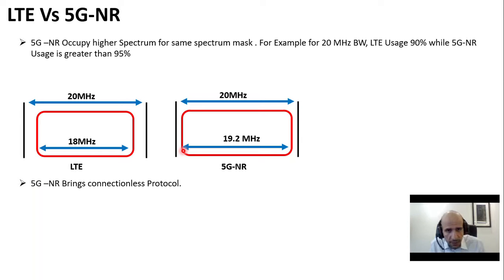This is because in 5G we are using filtered OFDMA, so we can use more bandwidth in the case of 5G technology. So we can say the spectral efficiency will increase in 5G NR. There are some other reasons as well, where the difference comes from the tighter RF requirements: tighter emission, adjacent channel leakage ratio (ACLR), and selectivity requirements, both for TX and RX, in 5G NR technology.